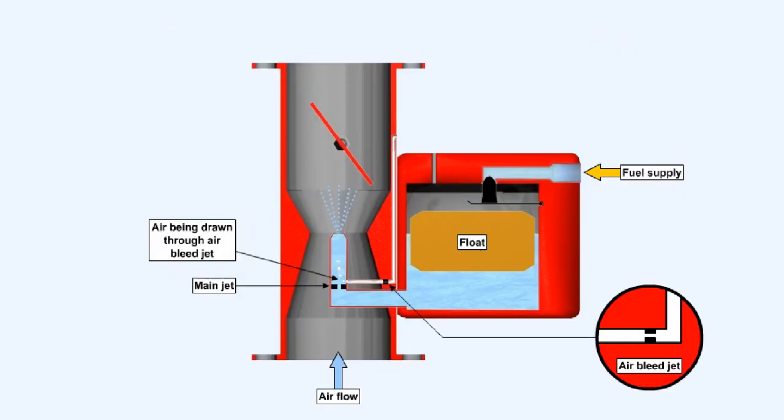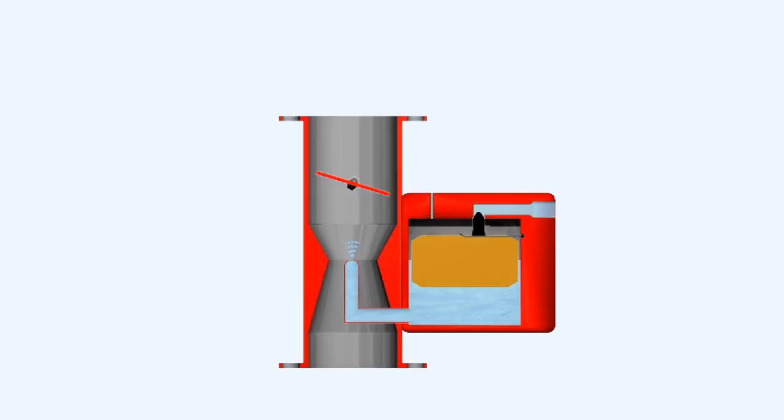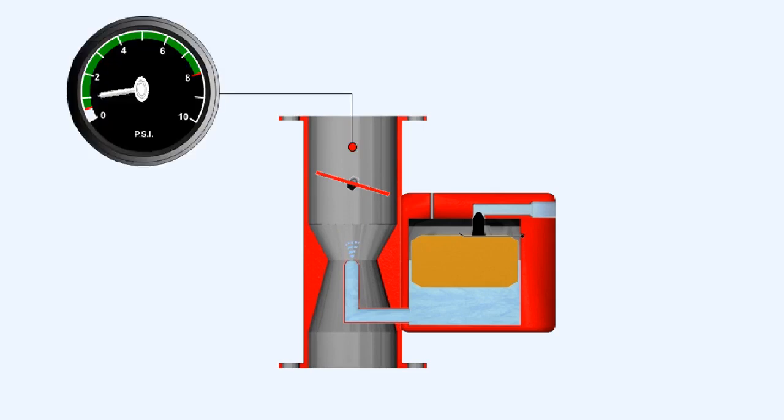This animation illustrates the principle being used on a basic carburetor. At low engine speeds, the volume of air passing into the engine is so small that the depression in the choke tube is insufficient to draw fuel through the main jet. Above the throttle valve, however, there exists a considerable depression, and in some carburetors this is used to effect a second source of fuel supply for slow-running conditions.